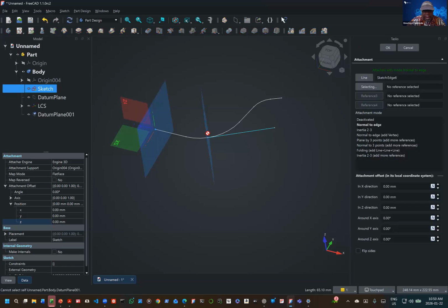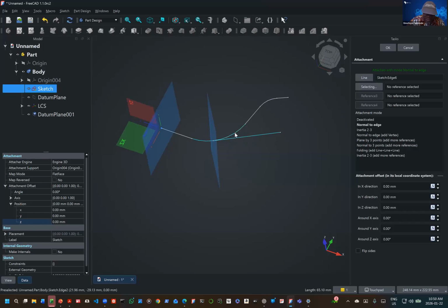So you see, let me rotate it so that you can see. At this point now, because this line is tangential to this curve, we choose this point so we can see that this datum is now perpendicular to the curve at that point because it now has this tangent and the point. So if we want to take a datum that is perpendicular at a point to a curve, we must first of all supply the tangent at that point.